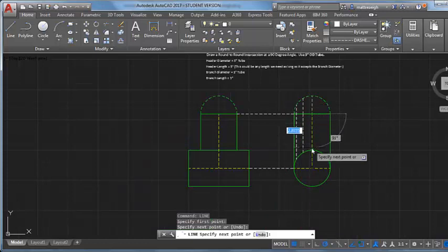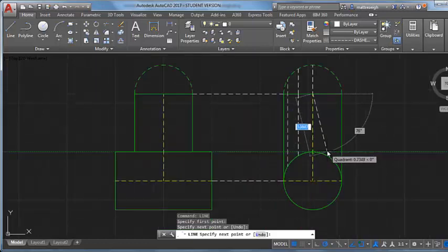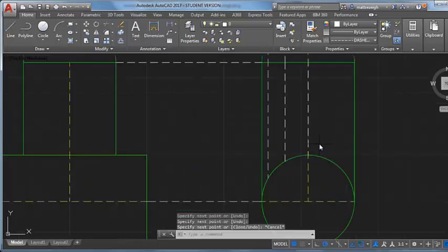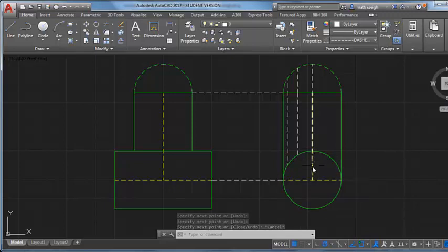And all right. And I think I'm actually going to do that one over the top of my center line, just because that actual center line was all the way down to here, and the actual branch ends when it meets that header. So I kind of need a length of line. If I think of these things as telling me information that'll help me develop a flat pattern branch, I need to be able to copy a line, and this actual center line would have been a little bit too long. So anyway, that was just me thinking ahead a little bit that I need that measurement.